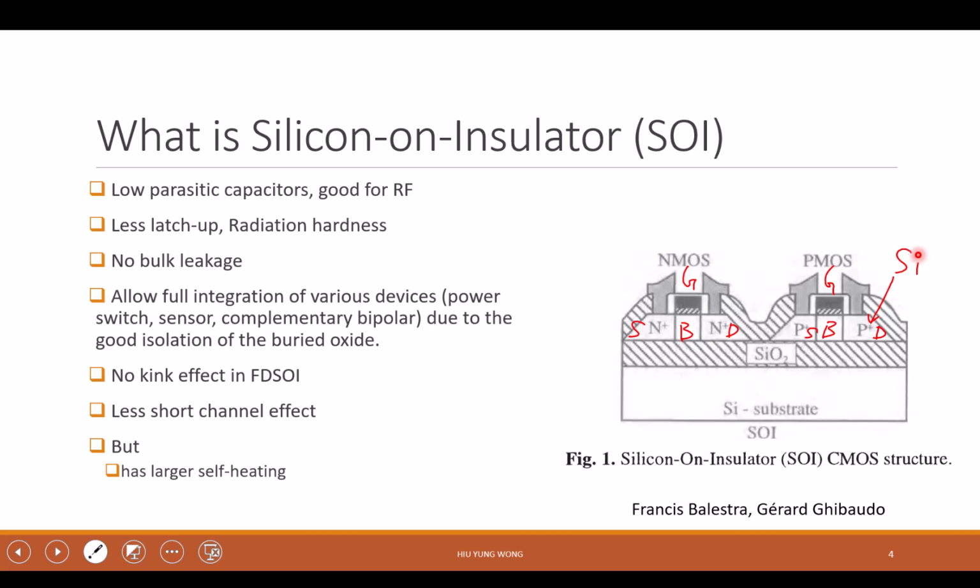And now you might understand why it's called silicon on insulator, because underneath we have the insulator. Usually it is silicon dioxide, for quality control, because it provides better interface and quality. This is why we call it silicon on insulator. You basically build a transistor on top of it. When it is on insulator, the rest doesn't matter so much. You can still have it on a silicon substrate. That is usually what we have.